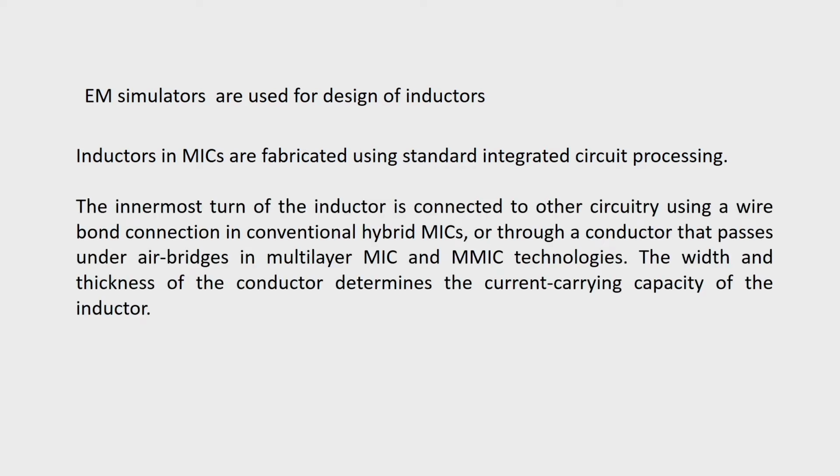The innermost turn of the inductor is connected to other circuitry using a wire bond connection in conventional hybrid MICs, or through a conductor that passes under air bridges in multilayer MIC and MMIC technologies.